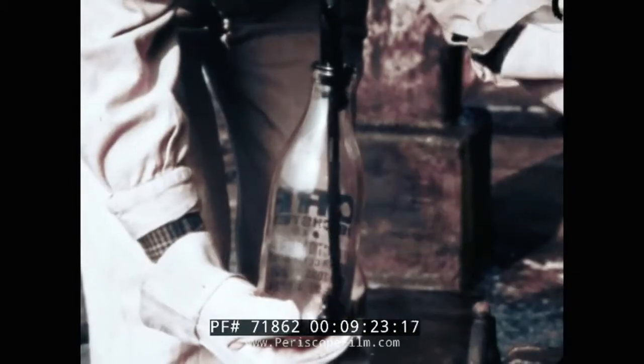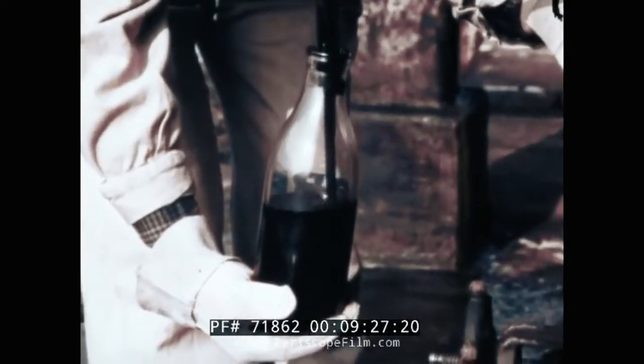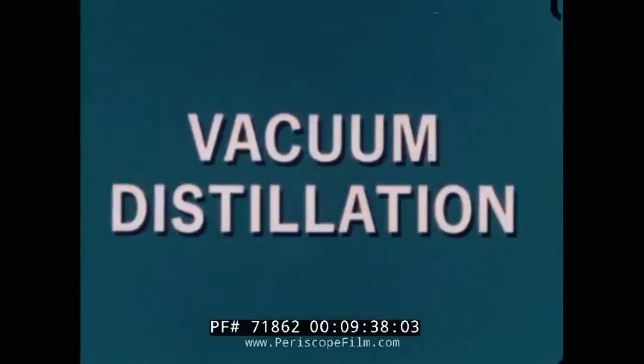The fractions in the residue boil at very high temperatures, some more than 1,000 degrees. At these temperatures, the molecules will crack apart before the fractions boil. To prevent this, they must be made to boil at lower temperatures, by vacuum distillation.